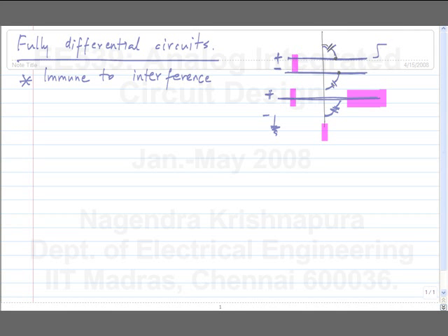So, if this rises up and this falls down and the coupling is physically symmetrical, they tend to cancel out, okay, because this black wire is like the line of symmetry in our circuit, in a fully differential circuit, okay. So, that will be at 0 volts because of symmetry. So, a signal represented like this as a signal between a pair of wires will not interfere with the other signals, okay. It is more immune to interference, but it also causes less interference, okay. So, good both ways.